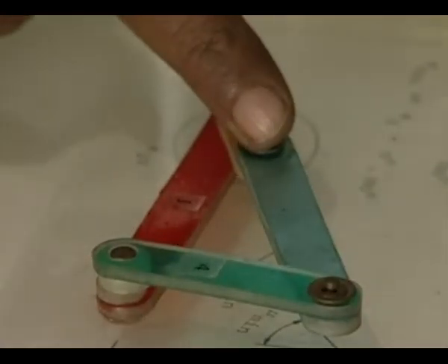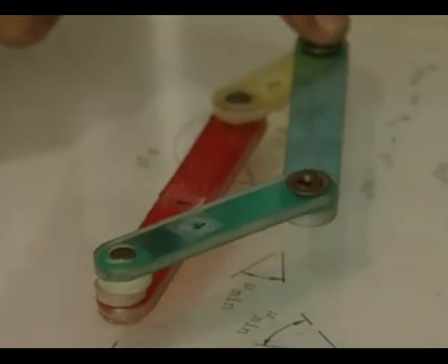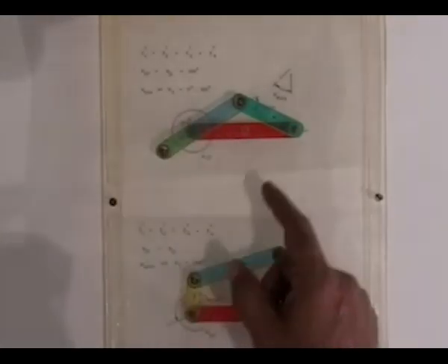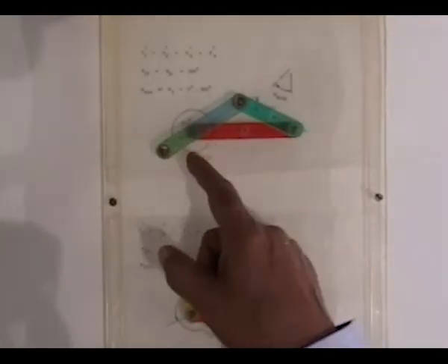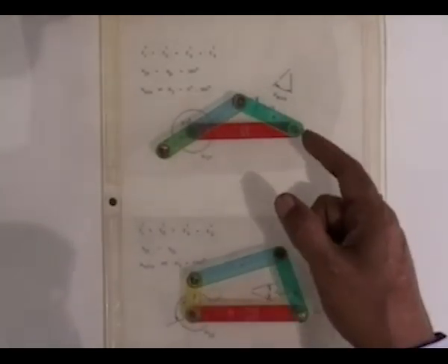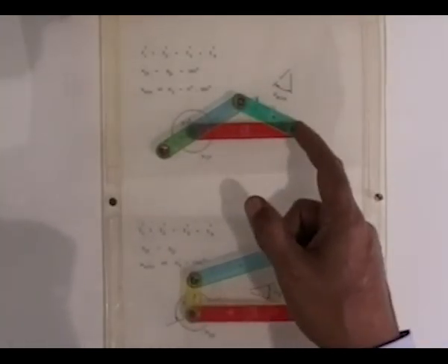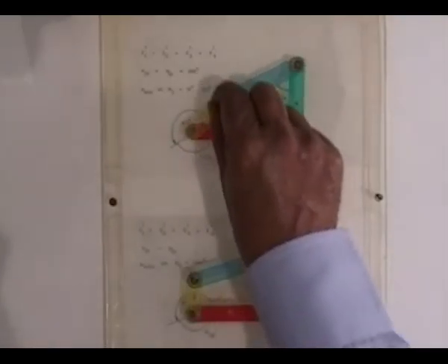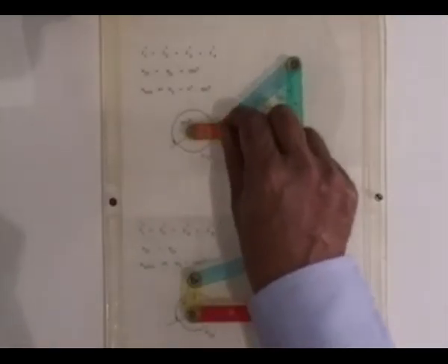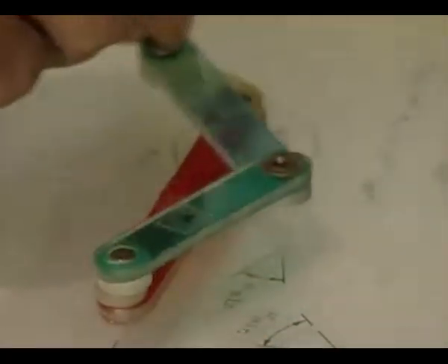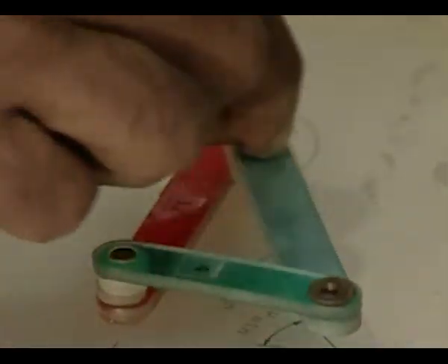Now, as it rotates through 180 degrees, again the crank and the coupler become collinear, giving rise to the other extreme position of the follower. As a result, in this 4R linkage, if the crank rotates at uniform speed, the forward and return motion of the follower takes equal time and there is no quick return.